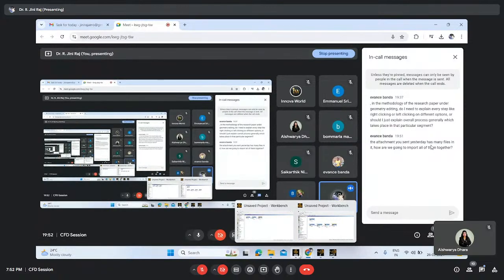Because we are doing analysis, we will get results in the form of CL and CD. So for 2 lakh elements, you are getting a CL value of 0.445 for a particular angle of attack. Let's say the angle of attack is 3 degrees for a particular wing or fuselage or whatever. You got one value for that element size of 2 lakh.